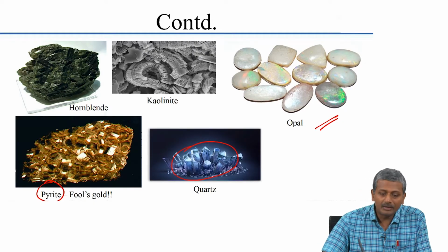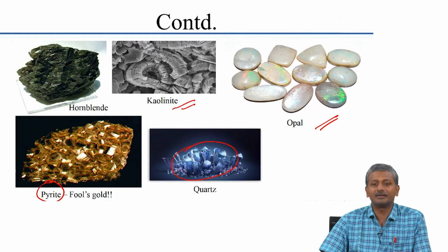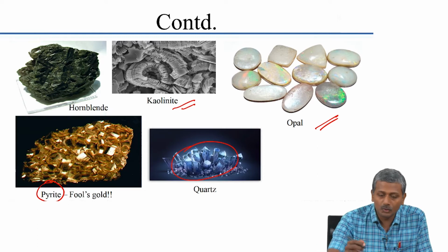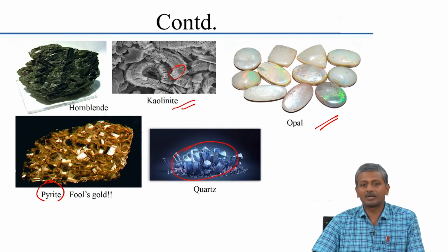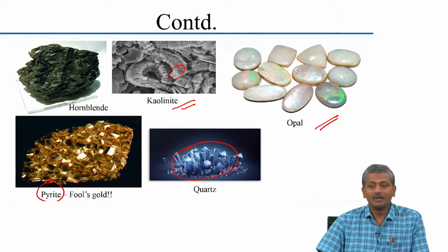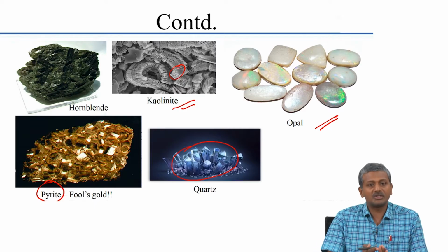And kaolinite, this is a microscopic picture of kaolinite, which shows you the very fine texture and also several layered aluminosilicate sheets which are connected to each other with some waters of hydration inside. When you heat up kaolinite to beyond 700 to 750 degrees Celsius, the water between the sheets gets removed and the sheets get activated.